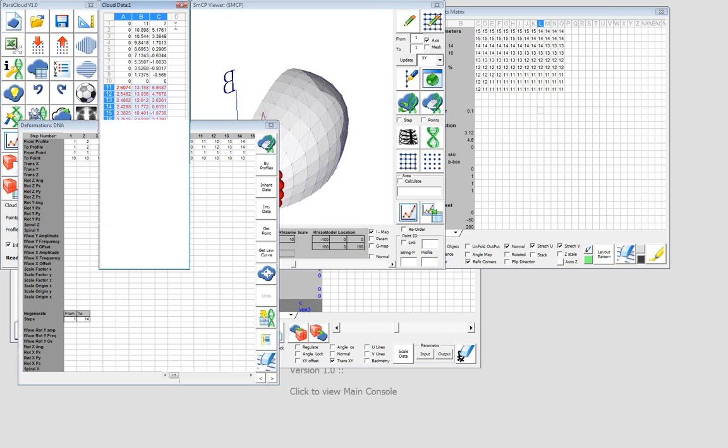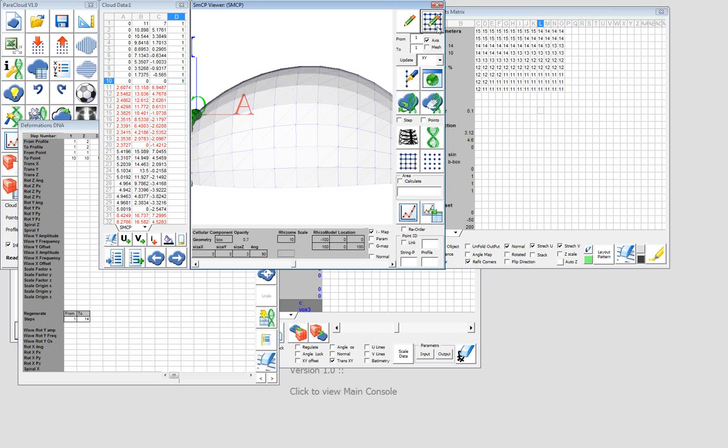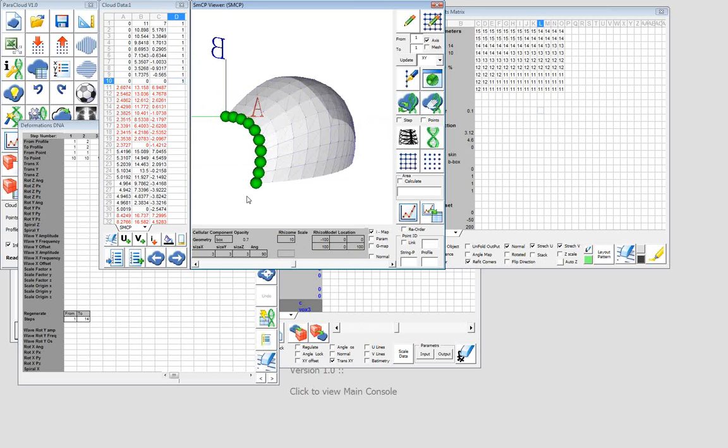Now, at the D column, we have a behavior toggle, and this toggle is set to 1, which will open all degrees of freedom, 0 will block, or I could actually edit different types of degrees of freedom to block different behaviors. I will set everything now to be 1, so all degrees of freedom are actually allowed. And if you visualize that, you will see that now it's represented in green.